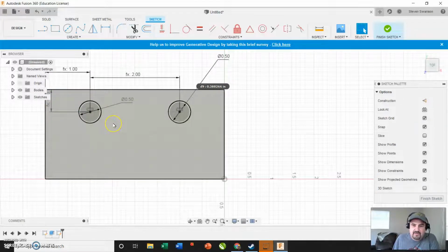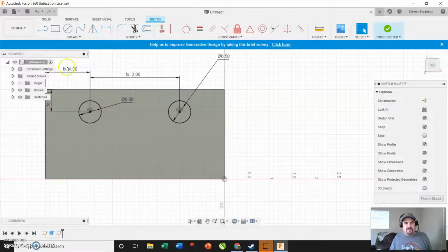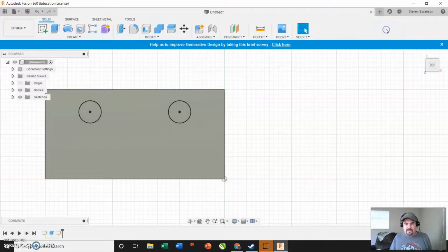You don't want colors. I mean, it'll still work if you don't do it, but that just means there's something you weren't looking at and you didn't care about. And usually you should care about pretty much everything in your drawing and where everything is. It's very important. So fully constraining is a very good tool and it's something you should do. And I also taught you about parametric constraining. Finish my drawing, right? And I'm done.